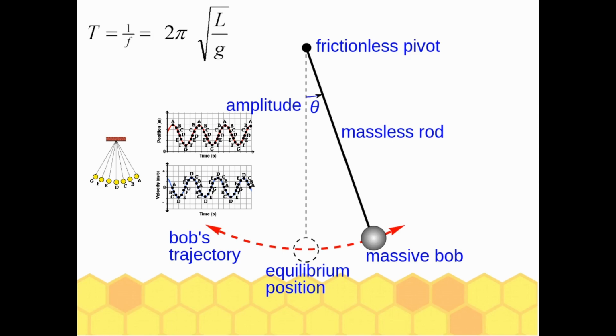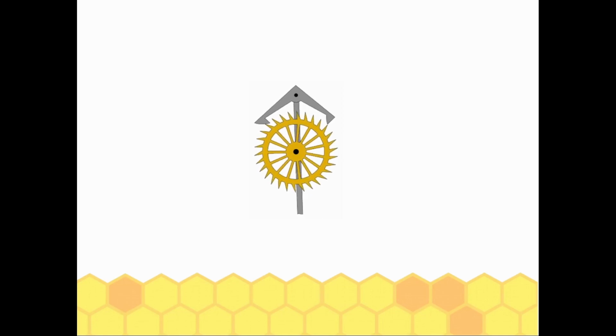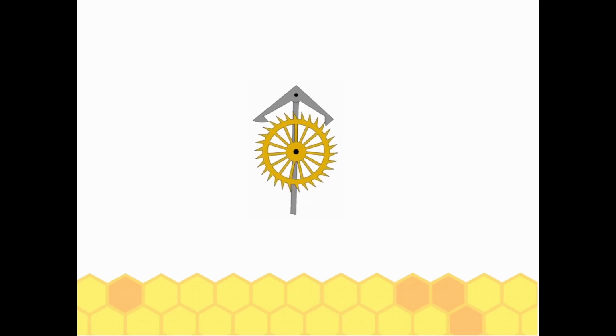And now, how do we use that to limit the rotation? There are many ways. We will choose something like this. Here, that yellow wheel is called the escape wheel, and that gray thingy that is attached to the pendulum is the pallet, I think. And as you see, it doesn't allow the escape wheel to turn faster than the pendulum oscillates. And because of the angles of the hands of the pallet, the wheel gives back energy to the pendulum, and it being much more massive than the torque applied to the escape wheel, will not change the frequency of its oscillations, but instead that energy will go into keeping the amplitude up, so the pendulum doesn't stop.